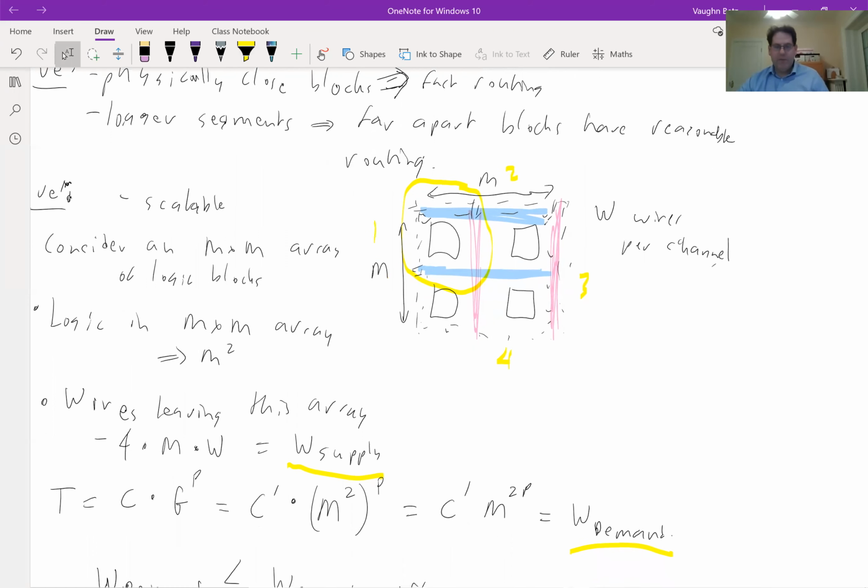So what FPGA manufacturers normally do is they make a whole family of FPGAs targeting a certain process node. So if you take Xilinx's latest chip, Versal, they're targeting a 7 nanometer process node with that. And they've chosen some channel width, and they'll make chips that vary in logic capacity by about a factor of 10. So they'll make some little chips, and they'll make some medium ones that are maybe 3 times that capacity, and some really big ones that are maybe 10 times that capacity. And they really don't want to redo the layout, because creating this layout for this basic unit was very expensive. They're going to have to redo it when they move to the next process technology. So that's okay. If they make a 5 nanometer FPGA, it's going to have to be redone anyway.